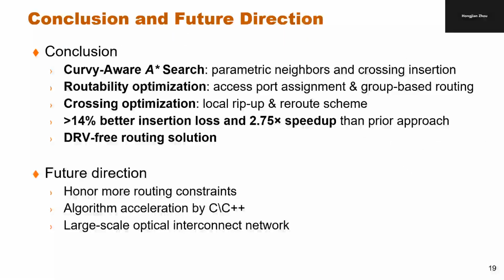Now, let me conclude our work and give future directions. LiDAR is an open-source automated detailed routing tool specifically designed for photonic integrated circuits. LiDAR features a non-Manhattan, crossing-aware A-star search engine with accessibility-enhanced port assignment and adaptive crossing insertion, congestion-aware group-based net ordering and objectives, and a crossing optimization scheme to handle unique PIC routing constraints while optimizing critical path insertion loss.